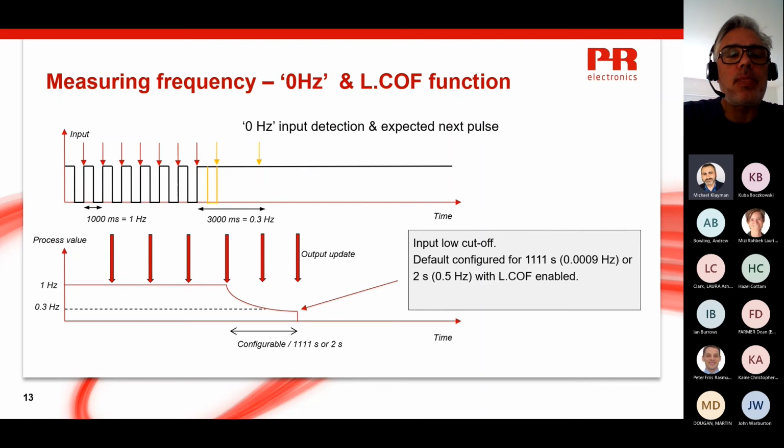The dispenser pump generates a signal with a period of 1 second, which equals 1 hertz. Here we have a trigger on the high level, the red arrows, which determines the start of the period. No later than 1 second later, we expect a transition from low trigger level to the next high trigger level to happen to establish a confirmation of our 1 hertz signal being measured.